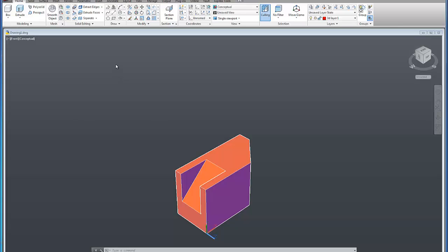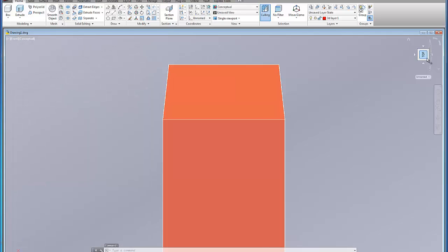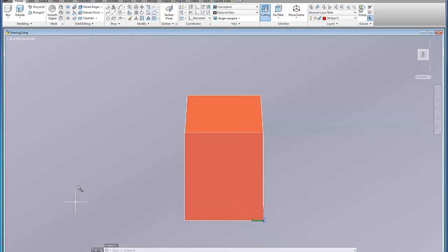And no matter what the shape happens to be, we're going to go ahead and get it started with a polyline. So again, I have to create a polyline shape, and I want the polyline shape to be along the end or end facing. Since I'm going to be drilling the hole straight through the object, I can't draw it from the top. I need to draw it from the side, so I need to make sure that the X and Y is on the side of the object. I'm going to go ahead and flip it around and tell it to be on the side of the object here. I'm going to choose the Polyline command.